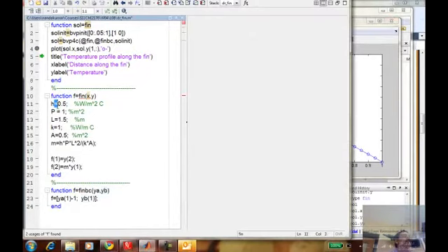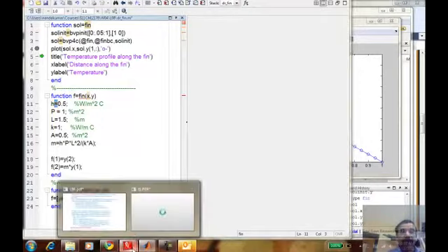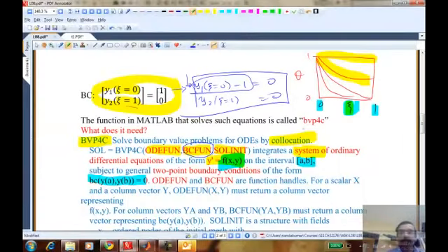For this, you need to understand the mechanisms that we talked about. If I'm increasing the heat transfer coefficient, what does the heat transfer coefficient do? It controls how fast heat is removed from the fin surface to the surrounding. So if I'm removing that heat very quickly, what would happen to the temperature profile? That is the question.